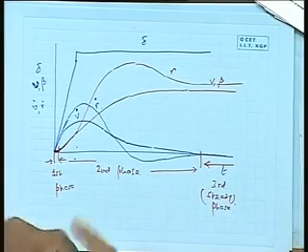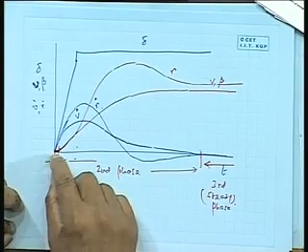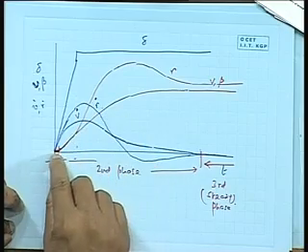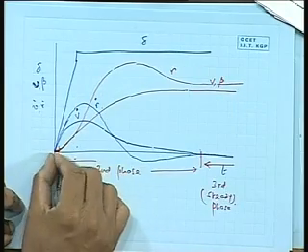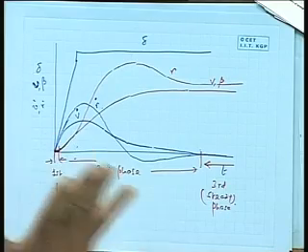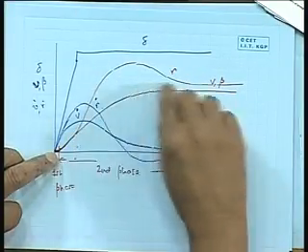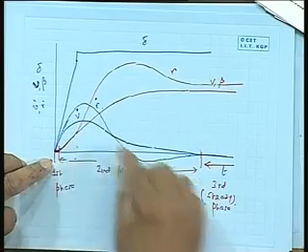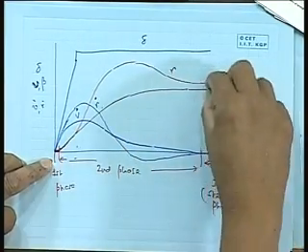Okay. What I mean is that the typical behavior will go like that. As you turn the rudder initially, immediately it will keep acceleration v dot r dot, but the increase of v and r, that is velocities, is very less. So there is a small time when we can call it first phase. It is not very important really, first phase, second phase, etc. Final third phase is the most important one. Then everything will be present non-zero, but eventually this acceleration will go down to 0, and velocities v and r will become constant.